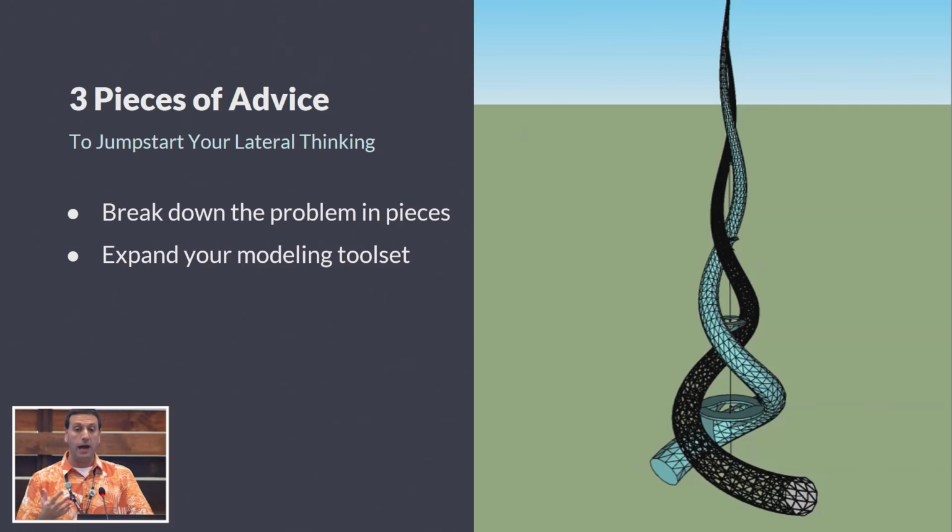And one day I thought, wait a minute, what if I draw a flat plane on the ground and I put my AutoCAD line work in a group above it and I use the drape tool to drape it down onto the plane. And I draped it down on the plane, and all of a sudden I had this SketchUp geometry that I could now actually work with, and I could just delete the AutoCAD line work, and I had flat AutoCAD line work on my plane in SketchUp. And using the drape tool was the simplest solution that I had never thought about before until I rethought the problem.